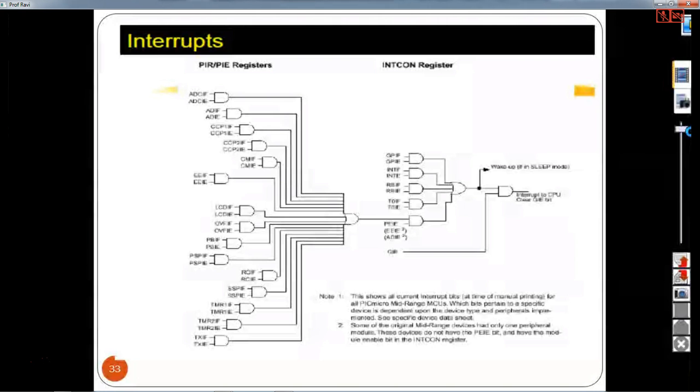So now the CPU registers. All SFRs in PIC are 8-bit size. This is what is important: the ALU works with the working register and the status register, and FSR is the file select register. Okay, and all SFRs, so program counter, 8 level stack. So these are the features, and all special function registers of PIC microcontrollers are 8-bit.